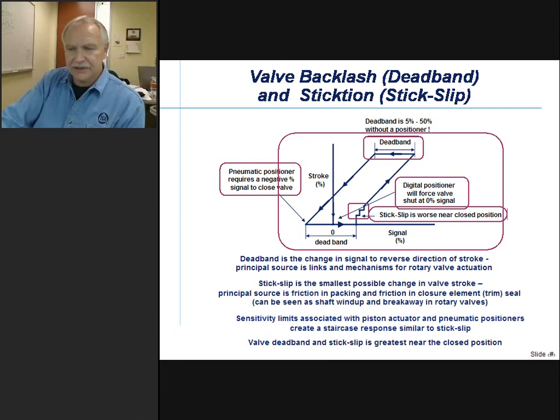We got in a little bit of trouble initially in that if we kept in our old output limits of -10%, there was not enough power at the low milliamp signals in some cases to keep the smarts going. And so those positioners, at least in terms of maybe their diagnostics, went to sleep until the signal and the milliamps got high enough to provide the power needed.